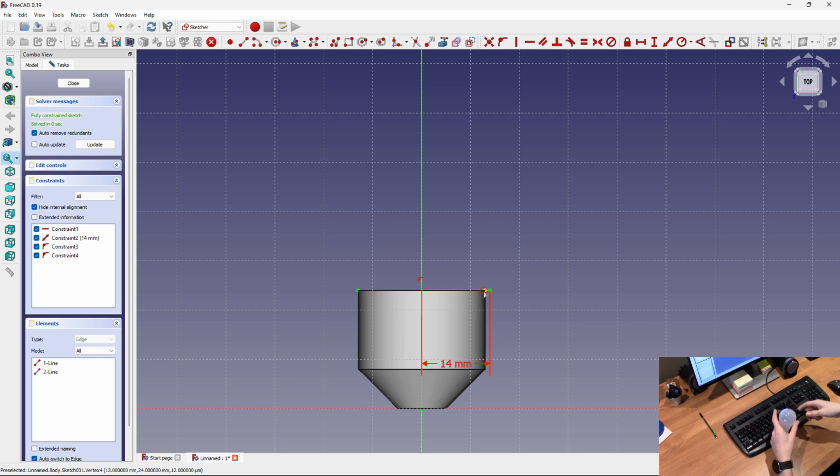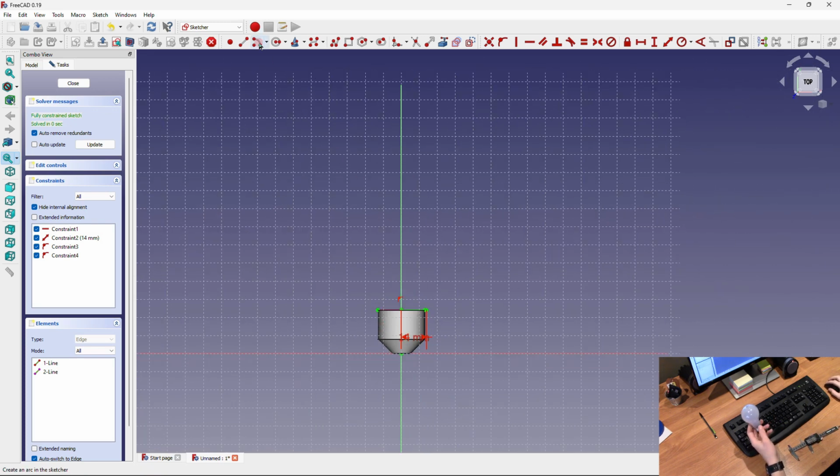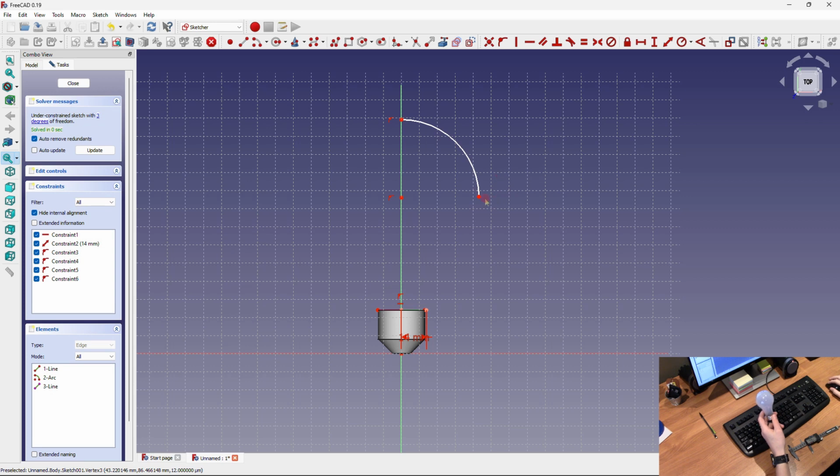At the largest part of the light bulb, it is 60 millimeters. So what we're going to need is a 3-point arc. You want that middle point on that center line because it's symmetrical. And you want the top point also on your center line. That'll be the very tip of the light bulb. And then the third point is going to end up wherever it joins.